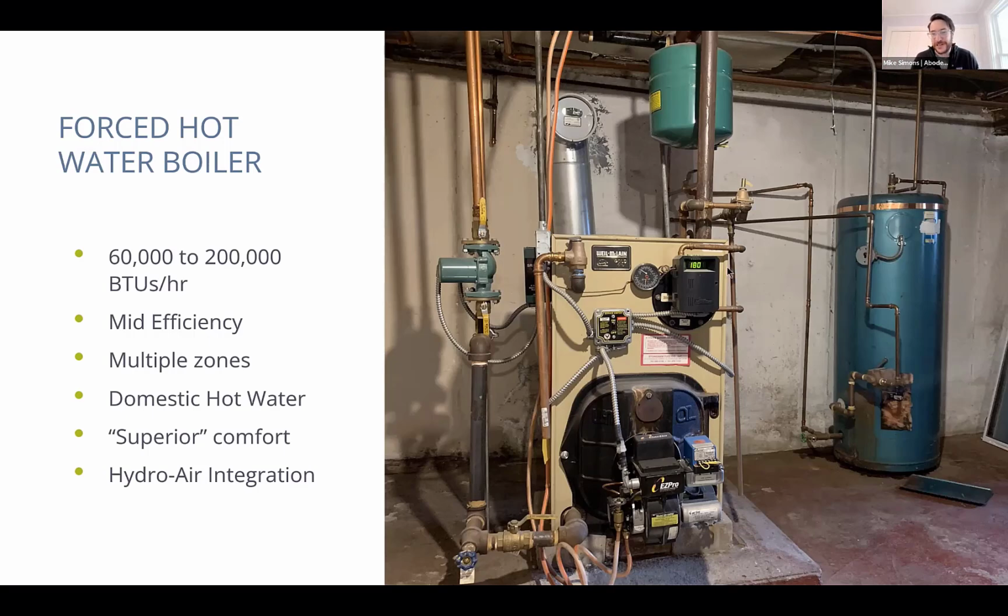But the forced hot water boiler, this is set at 180 degrees. So let's just focus in on that number for a second. The 180 degrees is what is likely going to every single baseboard, every single radiator in the vast majority of homes in Massachusetts. The only time that you ever see plumbers not set the aquastat to 180 degrees is if they have radiant floors or a hydro air system, which we'll talk about in a moment.